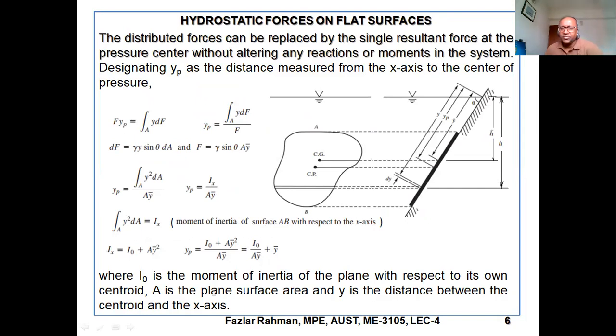Now, what we'll do, we'll figure out the location of the center of pressure. What we're thinking is that the pressure over here on the right, the force will be high. Our pressure force over here is low, gradually moving along the inclined distance or vertical height, and the force will decrease. So the resultant force must work through a point, right? We are thinking that the resultant force is working through this point, and this resultant force is F.